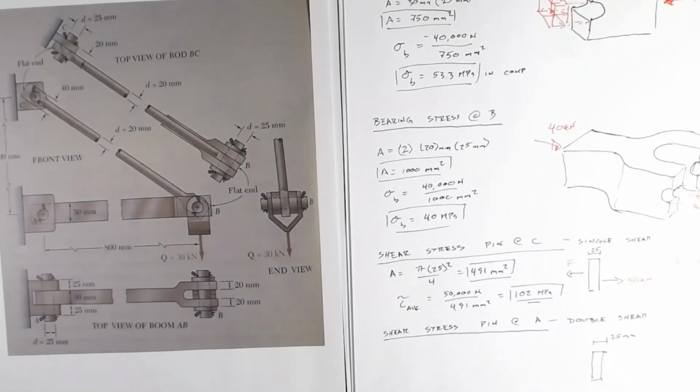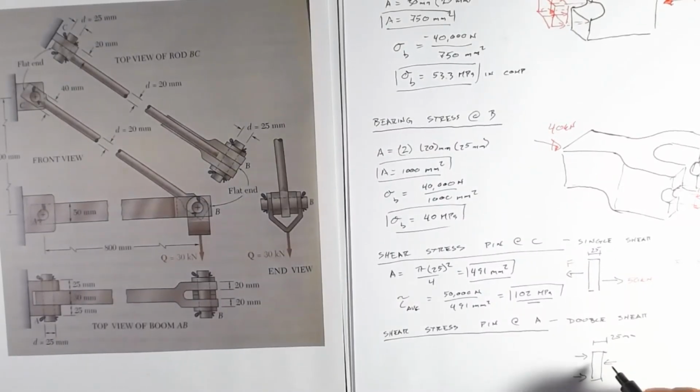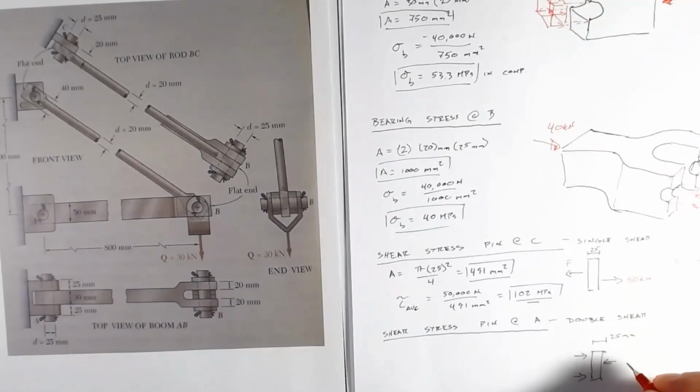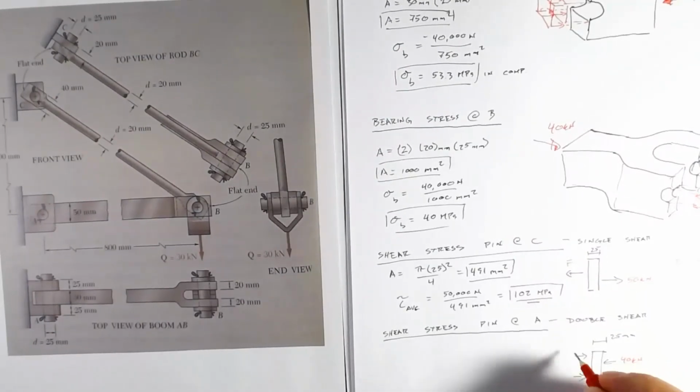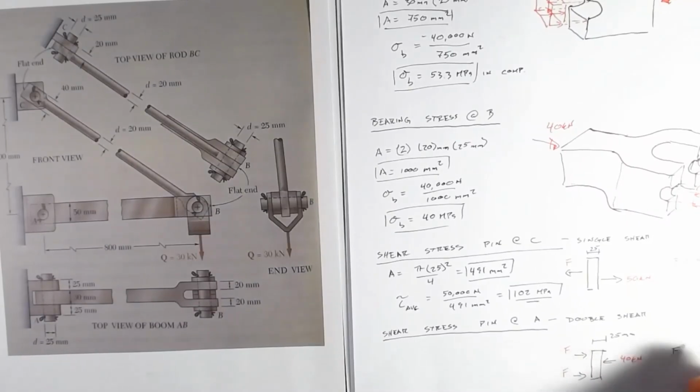But this time, we've got the 2 forces in from the clevis resisting it. So these are the bearing forces, and that's how we're trying to get this load in. So we have 40 kilonewtons coming in from the member, and we have the forces from the clevis resisting that. And we can see, pretty simple statics, these are equidistant. F equals 20 kilonewtons.